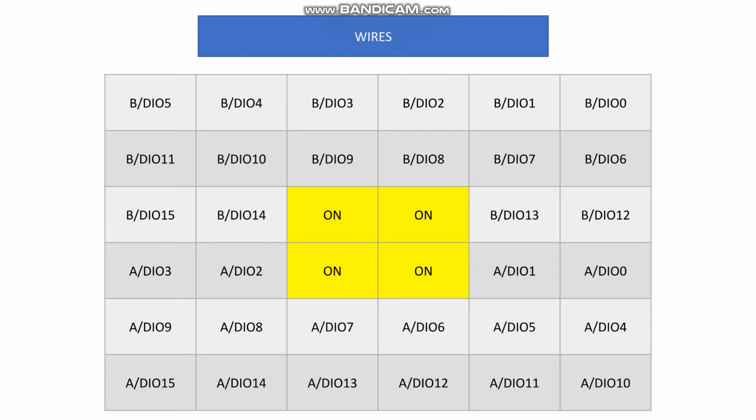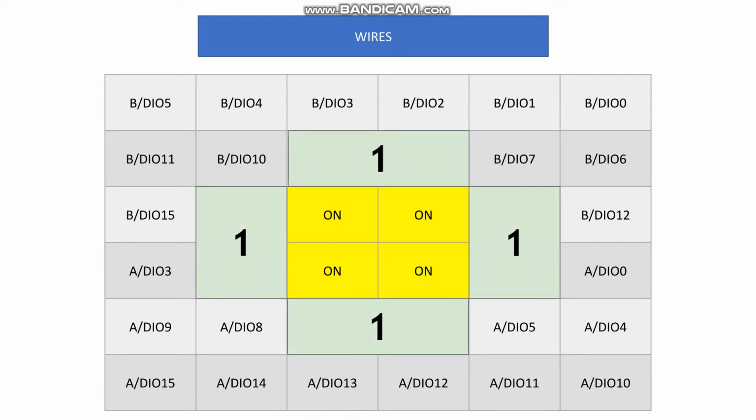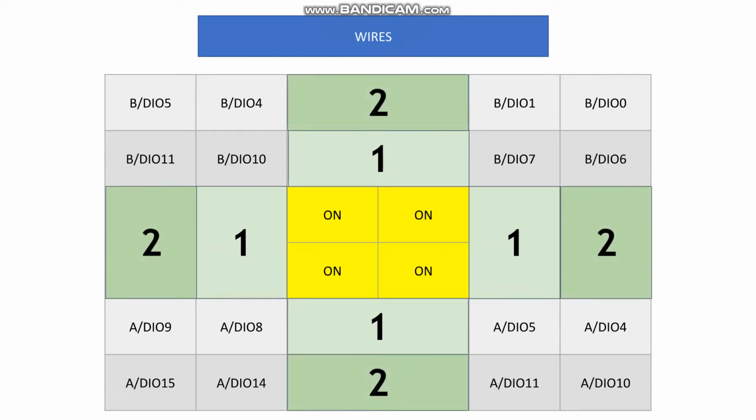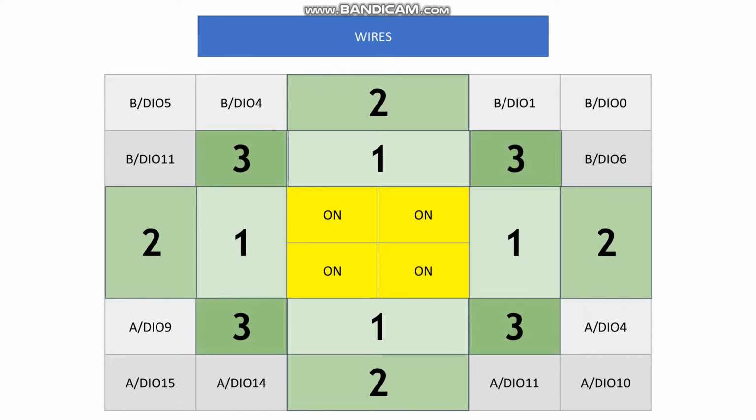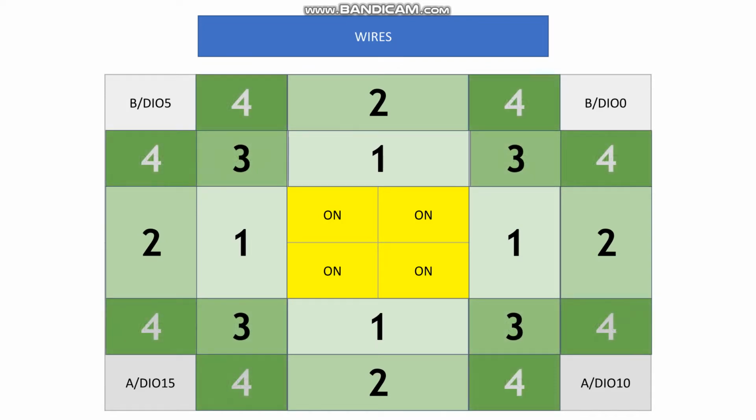Similar to the water flowing program, we are also using a threshold concept to get the LEDs to react to sound. In the previous example that we showed you, the first threshold was set at 1.64. So if the input voltage is any higher than this, the LEDs in that threshold will light up. The second threshold was set at 1.66, the third at 1.68, the fourth at 1.7, and the fifth at 1.72.